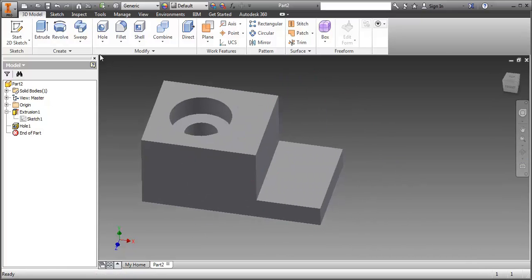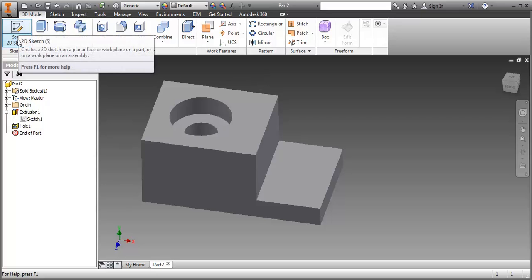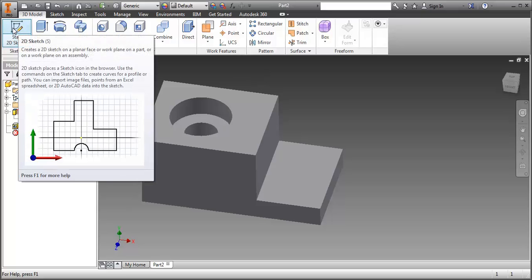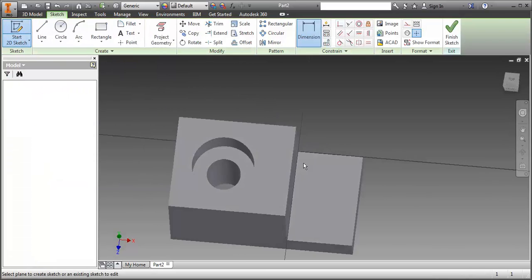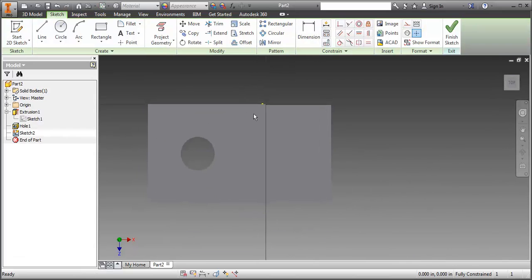So I'm going to go to Sketch. Notice again, the sketch is divided into two, so I'm going to hit the upper. That takes me right to it. Click that. All right, it rotates normal. In this case, I'm just going to draw a rectangle right there. Kind of eyeball the size, eyeball the length. Normally on a sketch, I do not put radiuses in. I use the fillet or round feature to put my radiuses in. So I leave everything square and boxy on a sketch.